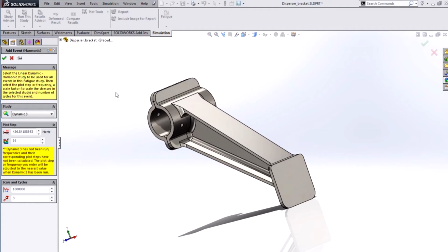So I could simulate that this particular suspension arm was vibrating 100 times at 50 hertz, 1,000 times at 500 hertz, and 10,000 times at 10,000 hertz. So in other words, I could simulate more like a real-world physical test, even a shaker table test, and figure out the accumulated damage, similar to what you've been able to do with fatigue study for other result plots before.